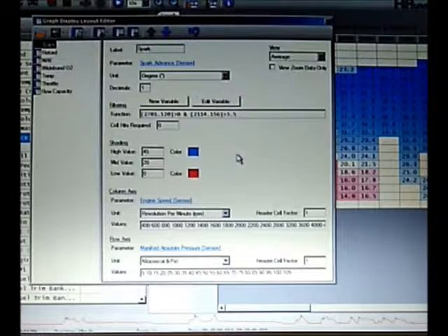It's just the way HPTuners did it. You can blame them. But basically you just have to try to figure out what PID is being logged here and what it's called in here. If you don't get it the first time, you can keep trying until you get it. It's unfortunate how they don't keep the wording the same.